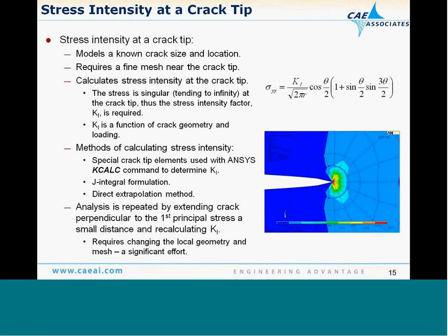So we know that if we can only see cracks to a certain level, we can hypothesize that there's a crack at least of the inspection size always existing in our structure. And then we can say, okay, what is the probability of this crack propagating?